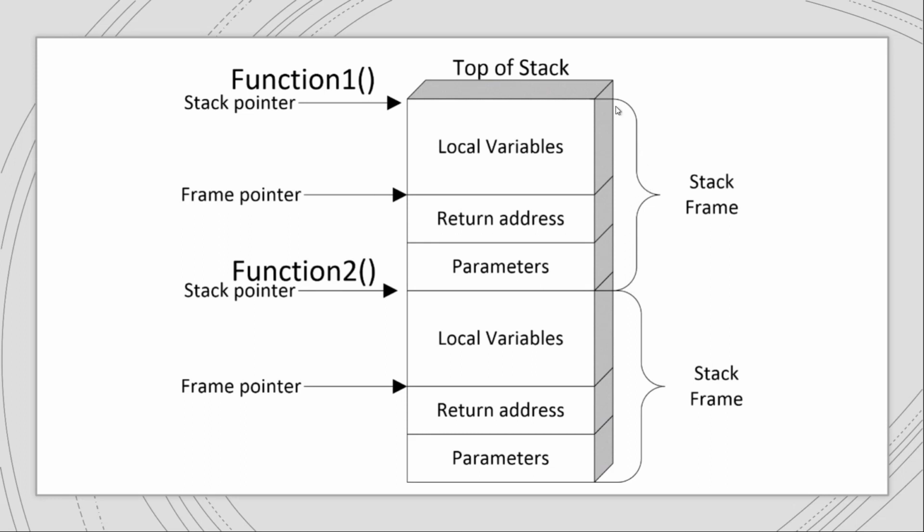For this function 1, the stack frame generally contains the parameter values and any register values which need to be preserved, like the link register which holds the return address, etc. I hope you got a clear picture about how these special registers are used and how the stack looks.